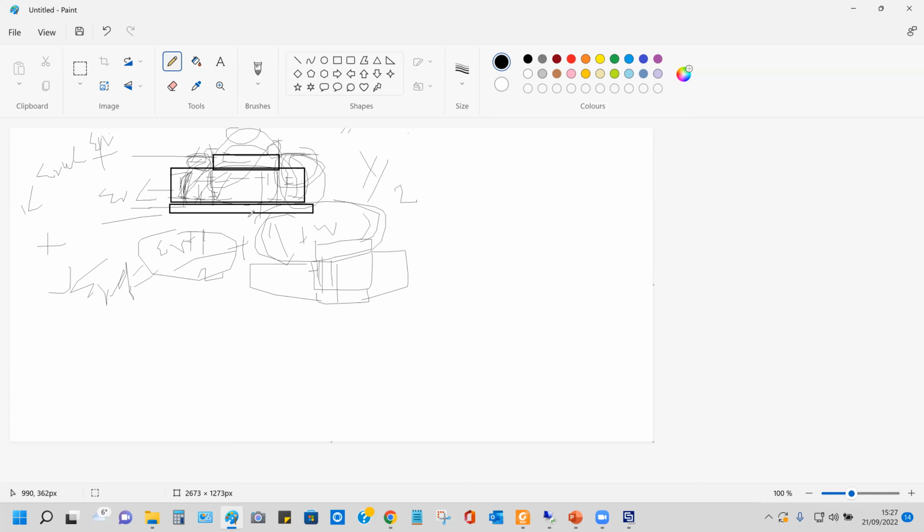Now, why I'm saying all this is that you can see the effective dielectric constant changing when you change the patch size. The effective dielectric constant is always going to change, right? Because the area that is interacting with the free space is going to change. For example, instead of a small patch, if you have a ring, you are having some interaction here also. The fringing field will be in this area also, so that also you are going to change.